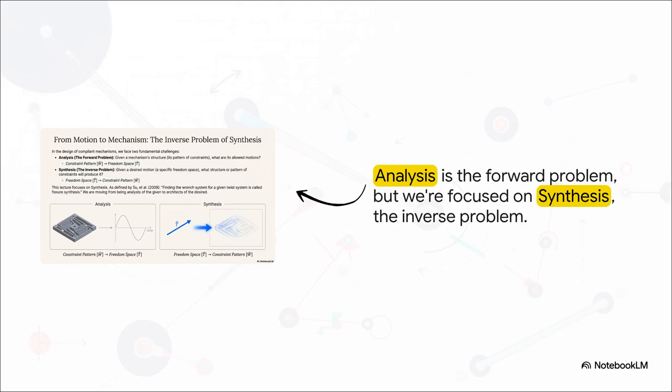Okay, so let's really dive into this whole idea of designing in reverse. This slide just captures that shift in thinking perfectly. See, on the left, you've got analysis. That's the forward problem. You're given a structure and you figure out its motion. But on the right, that's where we're headed today. Synthesis, the inverse problem. We get to start with the motion we want, and from that, we derive the exact structure that will produce it. We're literally shifting from being analysts of what exists to being architects of what we desire.